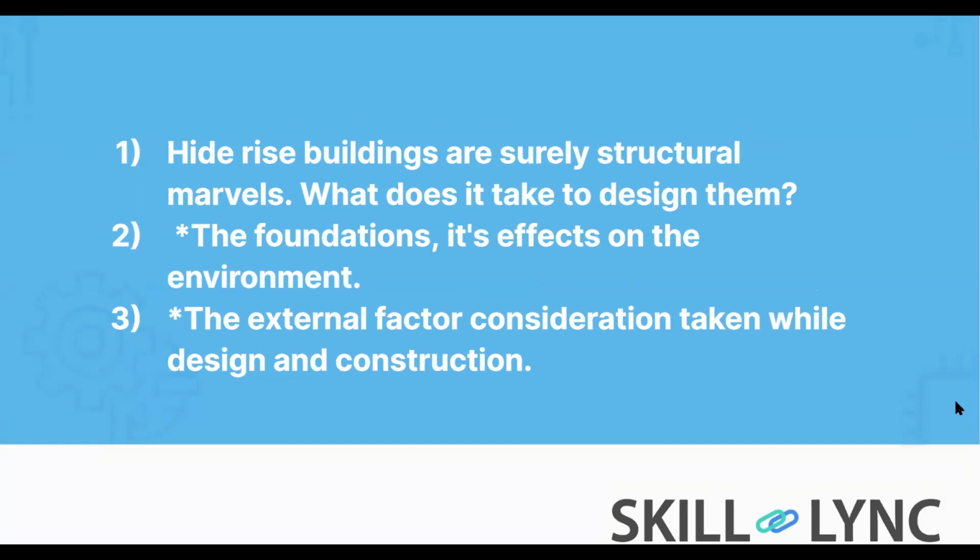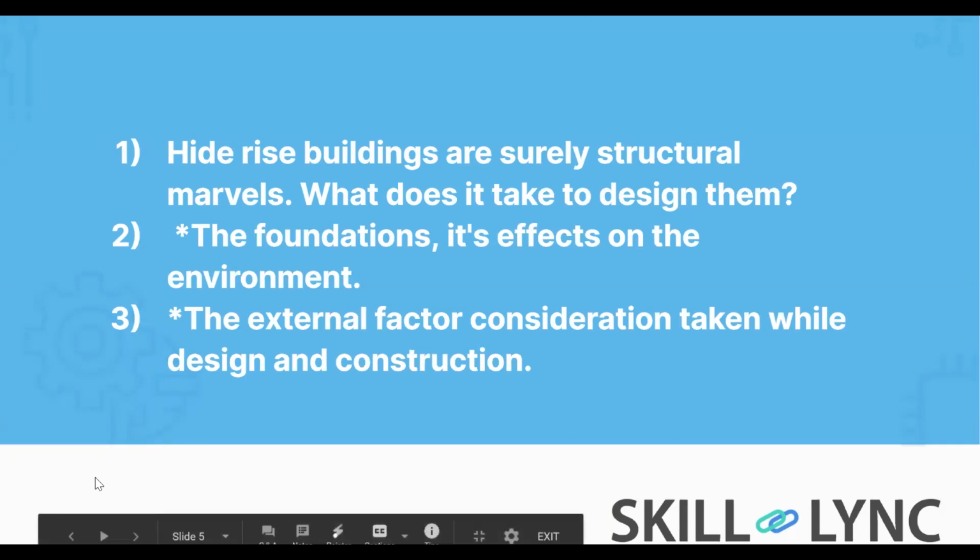And then the foundations. It's more of what is the soil in that location, what is your geotechnical capacity in that location. But definitely you will have a feasibility study before you go into design of such a big project. So there is always an initial stage of design where some design consultant will come and study the soil, what are the layers of soil, how much load it can take, and then we decide on what will be the foundation capacity of this building. And based on that, we decide on what will be the number of floors.